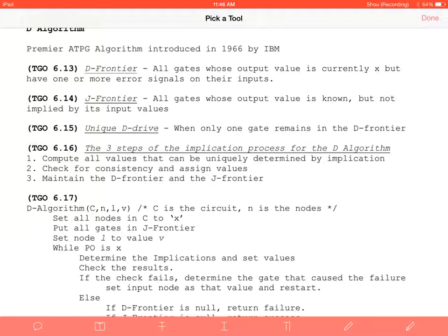Now, when you're doing this, we have our input values that we calculated based on our truth table, and we have a result of that gate. When that gate has a result on it, there's going to be some sort of process where that propagates to the rest of the circuit and reaches an output. That propagation is what's known as an implication. We have implied that if this is 1 and 0 on the inputs of this gate, or it's 1 in D or 1 in D bar, the consequence throughout the rest of the circuit is this.